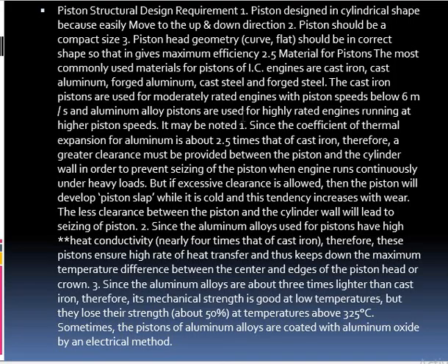Regarding seizing of the piston, since we use aluminum alloy, the piston should have high thermal conductivity and high strength, and it should keep a different temperature at the center and edges of the piston. We have to note this point whenever we design a piston. Aluminum alloy is about 3 times lighter than the cast iron piston.